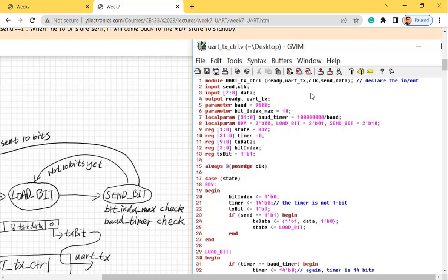So now we have a TX module, which we just need to design a top module for, right? A top module to wrap up your TX module, and in the top module you can assign a local parameter, can be a constant, like starting with 41, which is letter A. From there, right, and then connect that one to data or assign it to data. No problem with that. So for the push button, you know that it's going to vibrate, so you need a debounce.